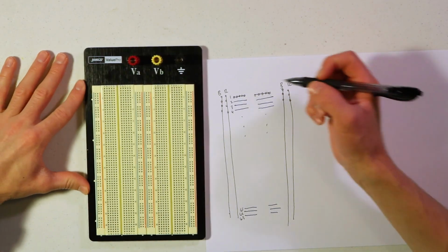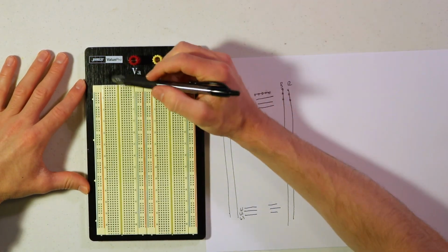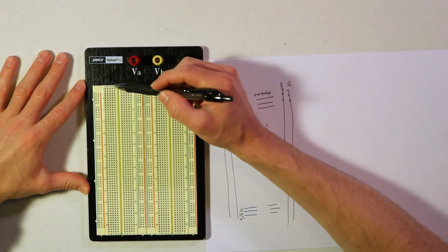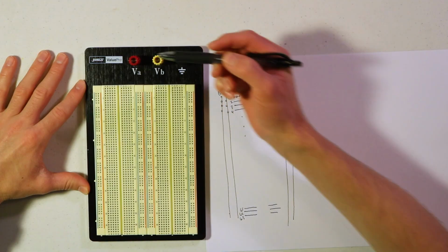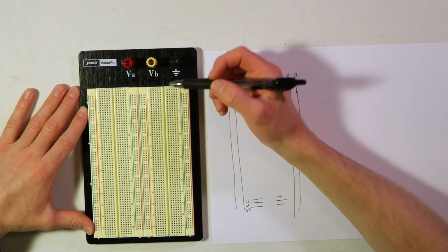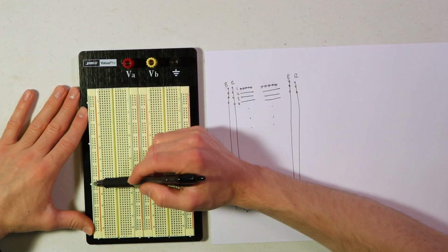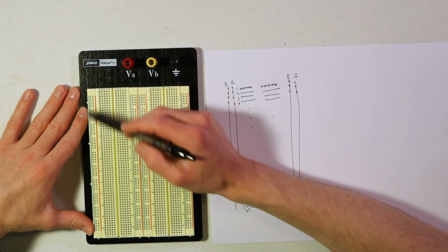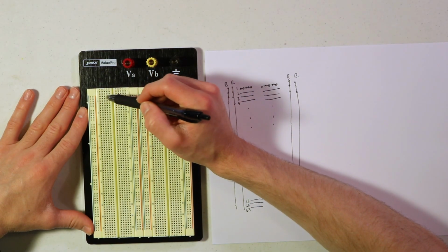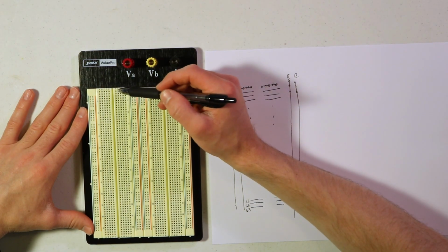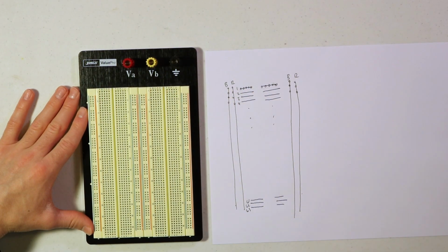So if you wanted to connect something from this side over to this side, then you'd have to put a wire that would go from this hole over to this hole. So that's how a breadboard is laid out. The main thing is the power rails. You've got blue line, red line, everything in blue is connected, everything in red is connected, and then the rows, you've got 1, 2, 3, so on, and then the same on this side, 1, 2, 3, and so on.